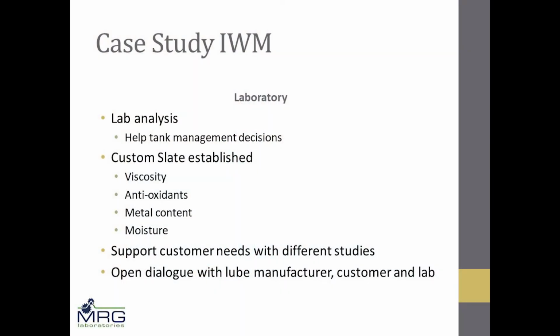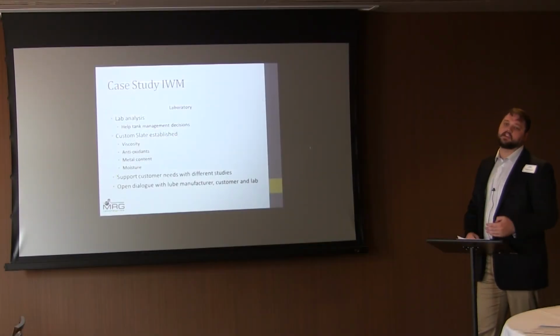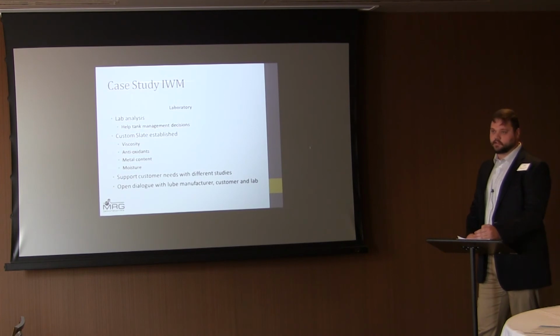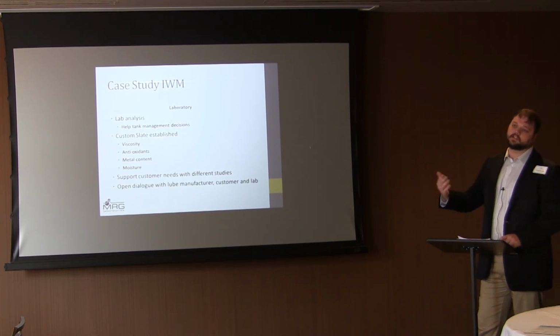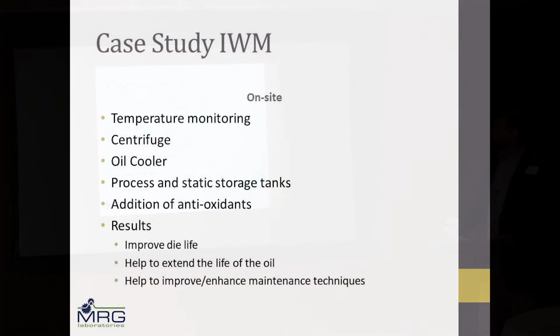Whenever a customer comes to us, John's come to us before, he wanted to understand viscosities at certain temperatures. So we did a study of his oil and viscosity, and then we were able to give him a chart and say, if you're at this temperature, you're running at roughly this viscosity of your oil. And that way he has an understanding when he goes to read his temperature and it says that his oil is this temperature, he has an idea of roughly the viscosity that the oil is running through the machines drawing oil, or drawing the wire, sorry. That's on the lab side.